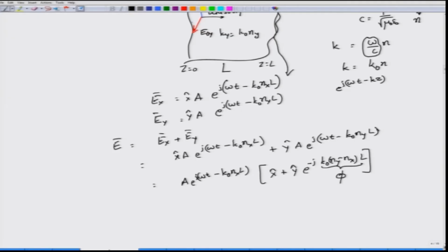So what you have seen is that there is a phase shift between the two components, and if in some way I can make this phase shift a function of the externally applied voltage, then I have obtained phase modulation, correct. This would actually become amplitude modulation because this phase modulation gets converted into an amplitude change as well.